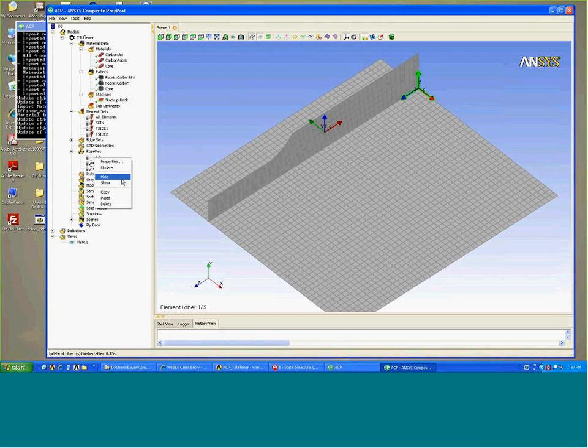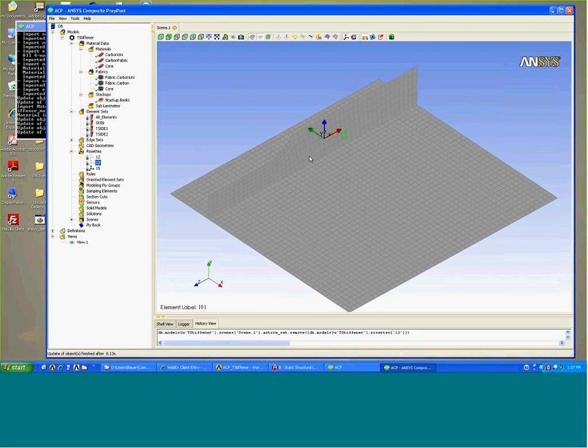This acts as a hide and show option throughout model building and post-processing. So let me hide two of these rosettes and keep rosette 15 here, as we'll coordinate our ply orientation direction. We can also create new rosettes here if we did not import them.